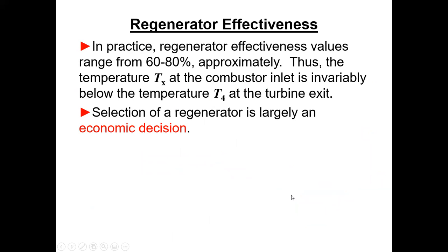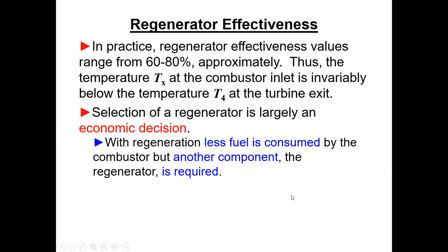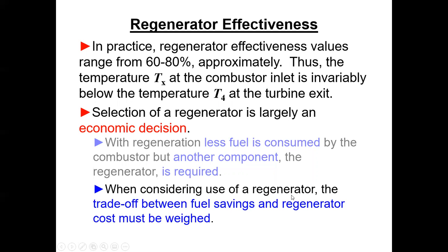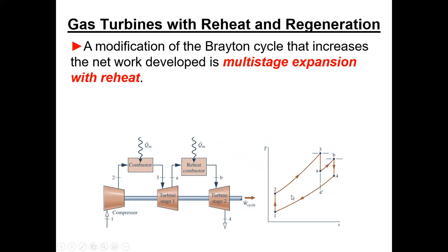He comments here, typically around 60 to 80%. It's basically an economic decision. If you buy a bigger one, you use less fuel and get better performance, but it's a trade-off between fuel savings and regenerator cost. So it's an economic decision.